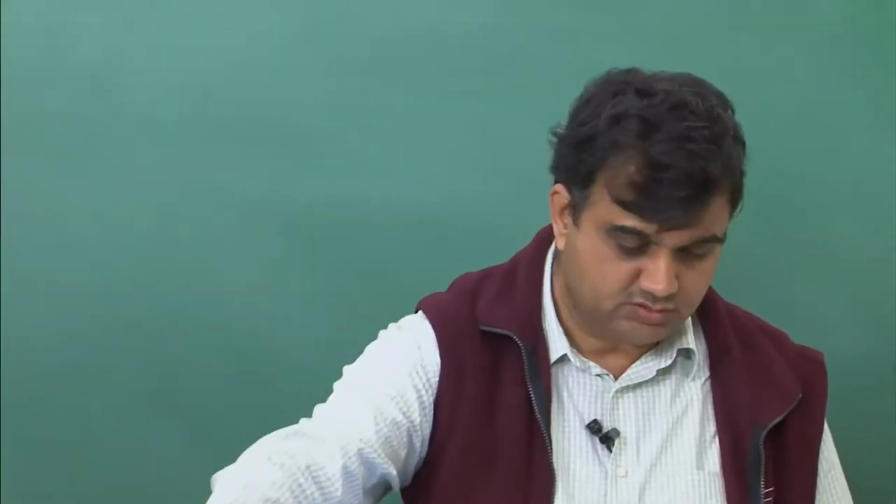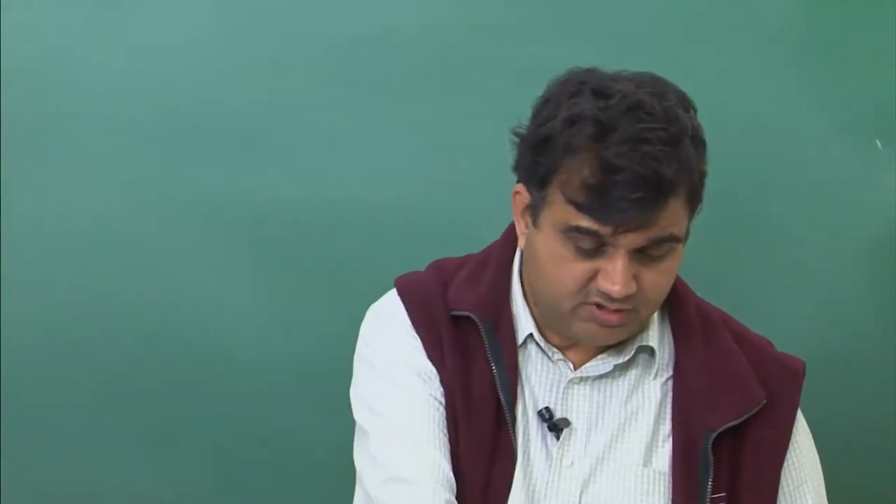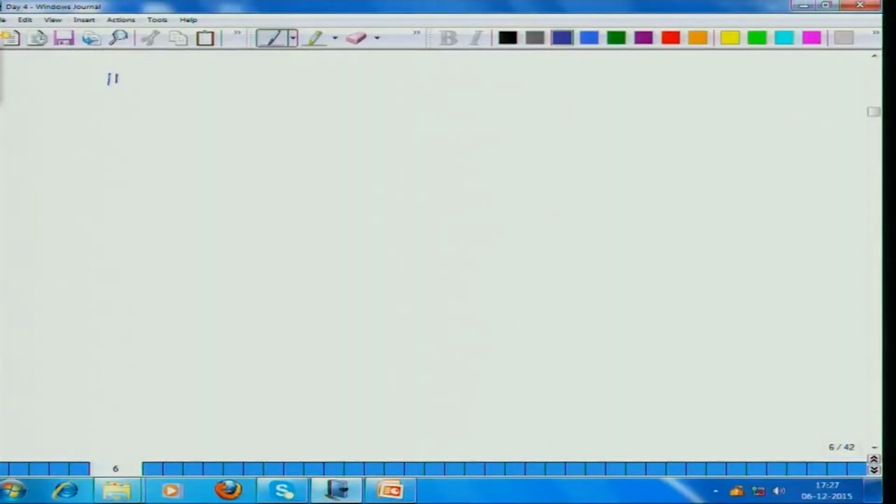Now I have introduced this notion of directivity. So it's important that whenever you look at a microphone, you also look at its directivity characteristics and make sure that it meets your needs. Now we will look at 3 different categories of microphones, and they are all related to this notion of directivity. But before that, maybe I'll spend another 3-4 minutes on something called incidence.